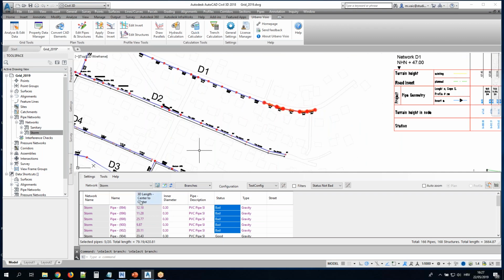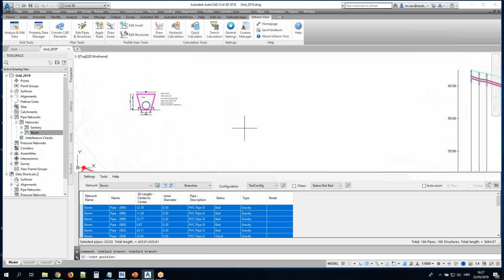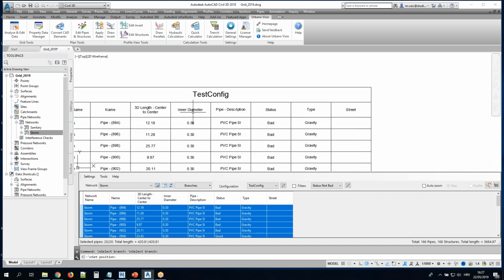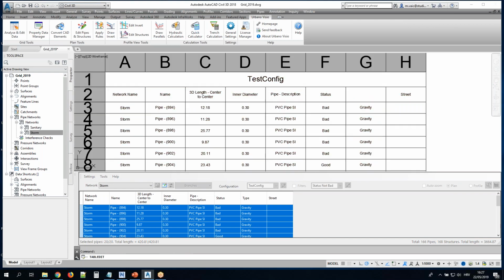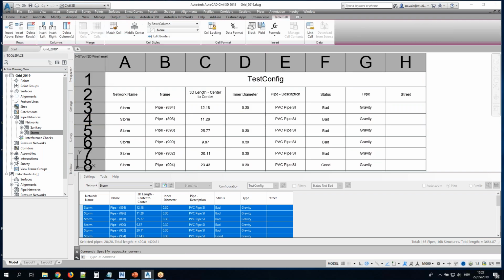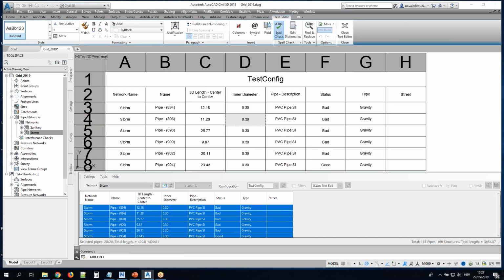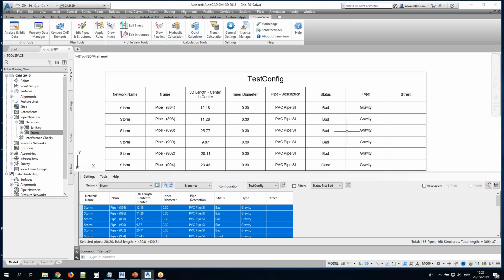Okay, one thing that you also can make is you can draw tables. So this is now an AutoCAD table. If you start to edit something, immediately the AutoCAD table design tools pop up. So you can add columns, you can add formulas if you want, and so on. Do all of these things.